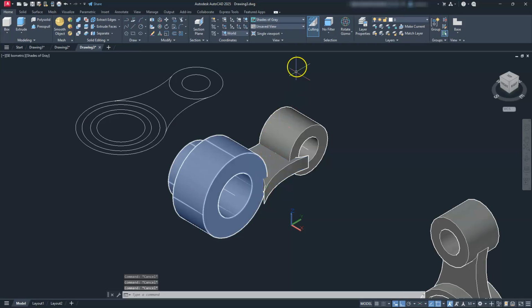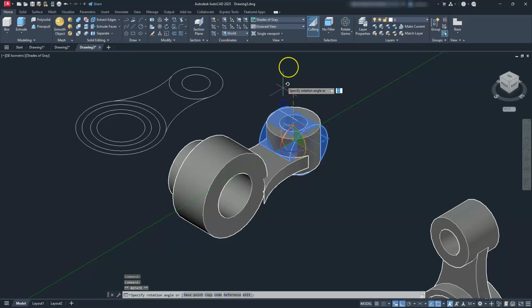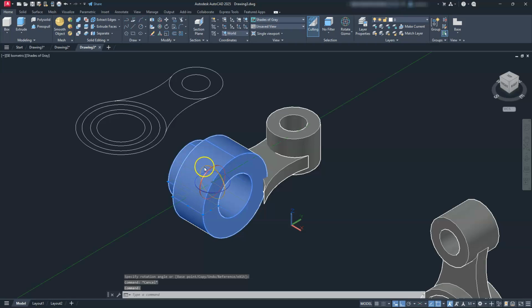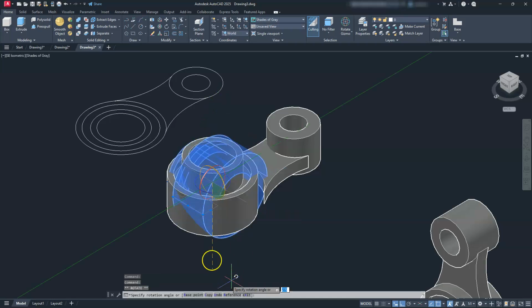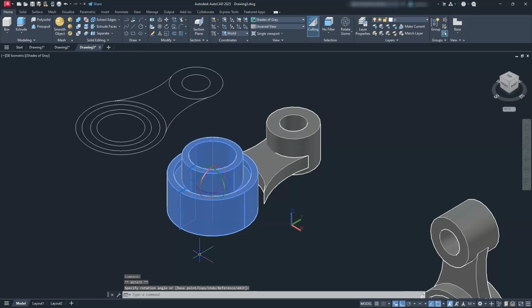This is where understanding the rotate gizmo gets really kind of interesting. We have some lines of revolution there, and those lines will stay there. So I'm just going to select them both and delete them. I'm going to start off by this shape here. I'll select this green axis, and I just want to stand this one up here. Let's escape out of here. Do the exact same thing on this one. So I'll select this one. And it looks like it went the other way. I'll come down this way.